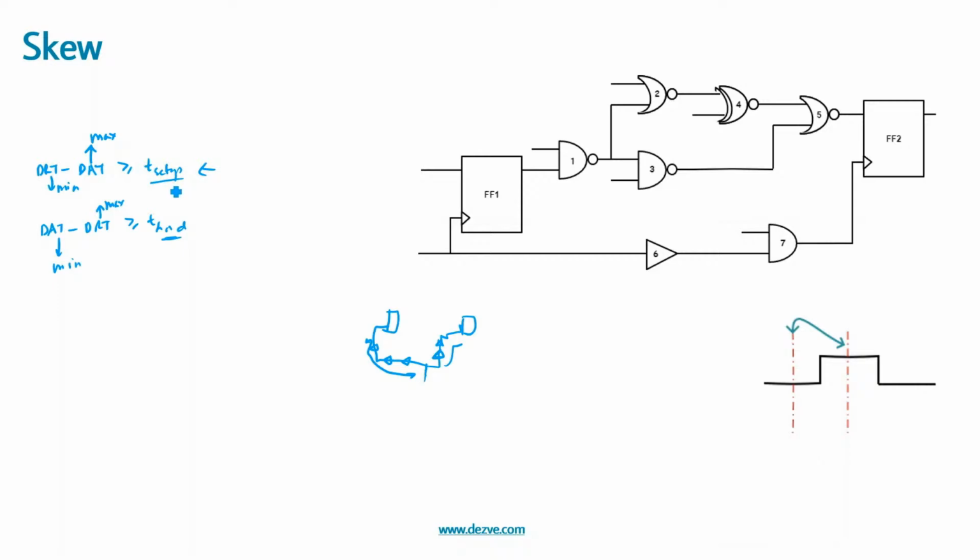So in this case, the ideal thing would be to compensate that skew on the clock path, correct? So suppose, assume without skew, after all max delays the data was here, and after all min delays the clock was here. So max of data, min of clock, correct?